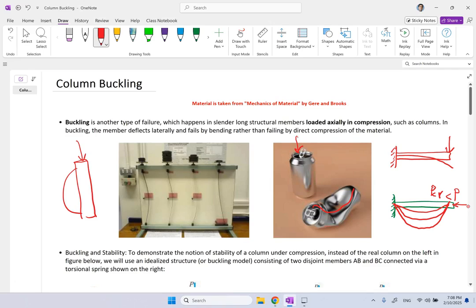Or on anything else, as long as most of the time they are tall and slender, so their cross section is not big. Those two factors, large length and small cross section, will cause this critical load to be small, as we'll see in Euler's formula, and the system to buckle, basically.